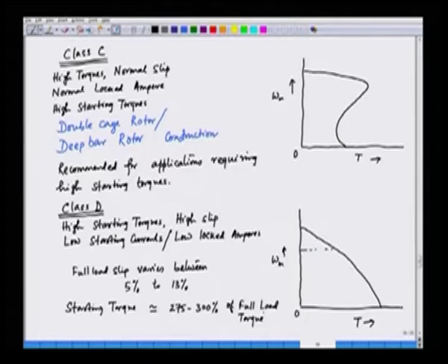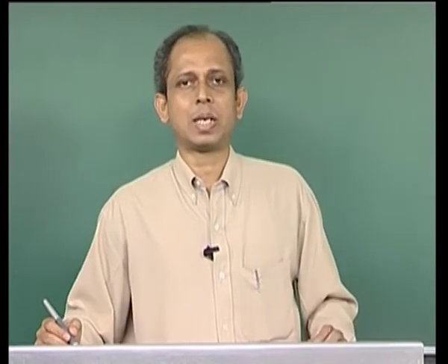So this class of motors are applied with punch presses applications. This is basically the class D motor having large rotor resistance, and they are applied in those applications where we require high starting torque. Now these are the classification of the induction motors.